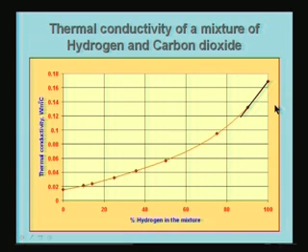That means that the thermal conductivity change between the carrier gas and the carrier gas plus CO2, which I was talking about earlier, is a small amount, and in that range I can use a linear relationship between the thermal conductivity and the percentage of CO2 in the mixture, because 80% here means 80% hydrogen or 20% carbon dioxide. So, in other words, I can say that 100 minus whatever value gives you the percentage of CO2 here.